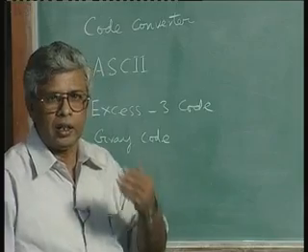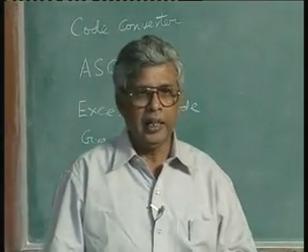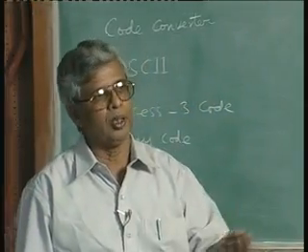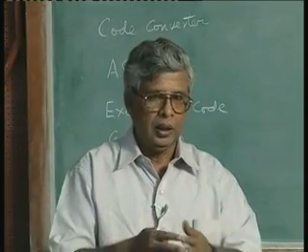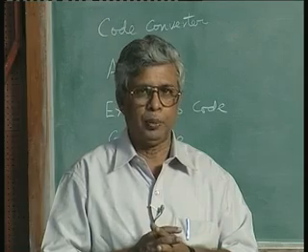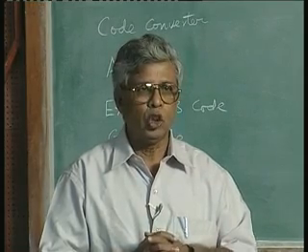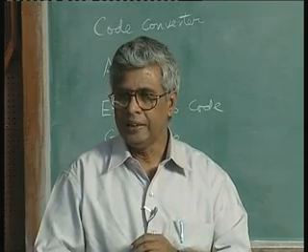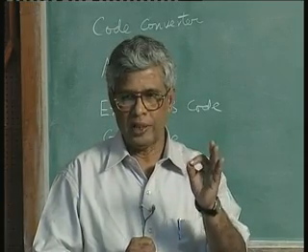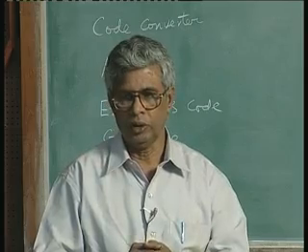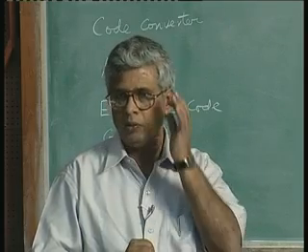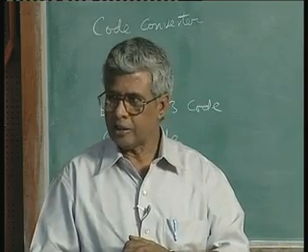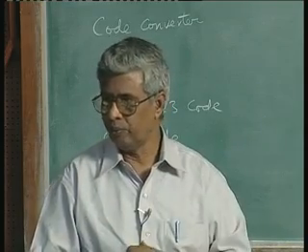Gray code is used for reducing the switching activity, they call it. Anytime you change a number from one code to another, zeros have to be changed to 1, 1 to become 0. Suppose I have a 4-bit number 0 1 1 1, with a 0 MSB, that is 7. Number 8 decimal is 1 0 0 0.